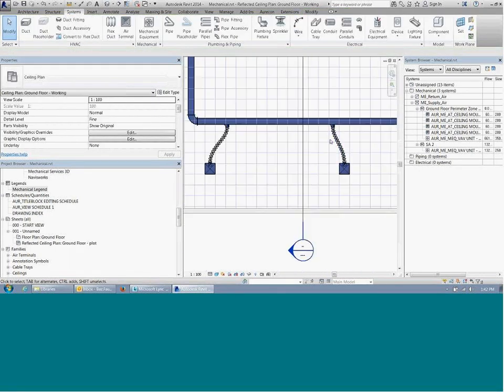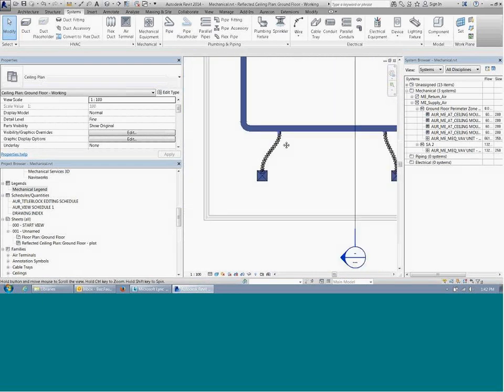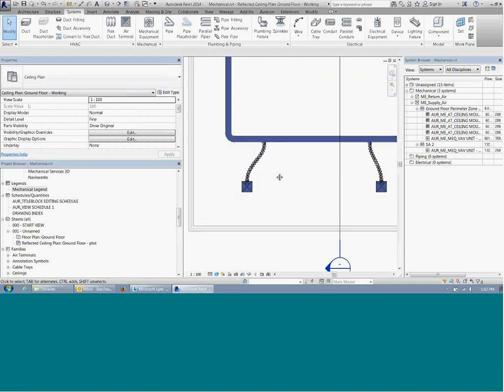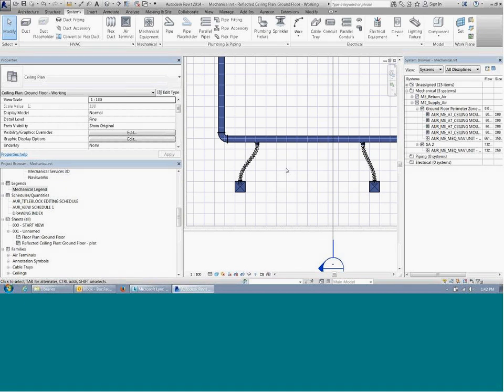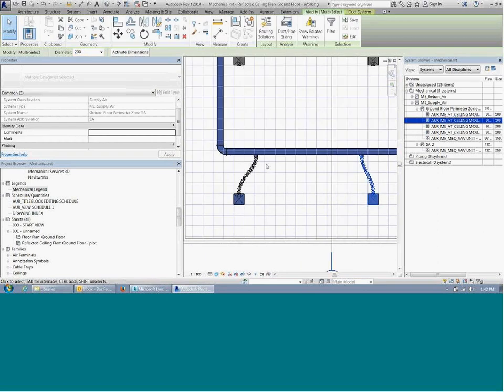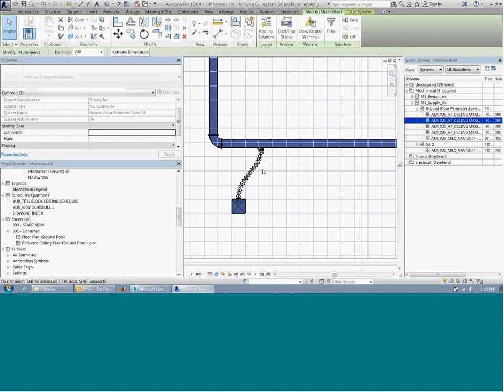You don't draw it straight. Actually, group. It's all right on a ceiling with tiles in it, because you can just pop open a tile and adjust the spigot. But if you had a plasterboard ceiling, you'd usually access the spigots by an access panel, and that's where you should group spigots together to minimise it, because if you had an access panel for every spigot, you could imagine what it would look like on the ceiling.